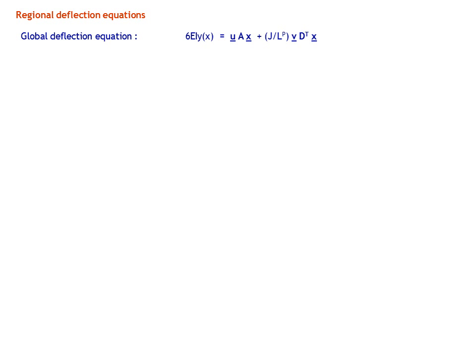Firstly, we'll go back to the multipoint load on a generic beam and the inequality for x, namely that A_R is less than or equal to x, which is less than or equal to A_(R+1), from which the deflection equation was derived. The distance to the rth point load, A_R, was given by the simple relation A_R is equal to A plus (R minus 1)B, from which we can see that A_1 is equal to A. This inequality makes it look like x must lie underneath the load only, but we can show that it can exist on either side of the load as well.